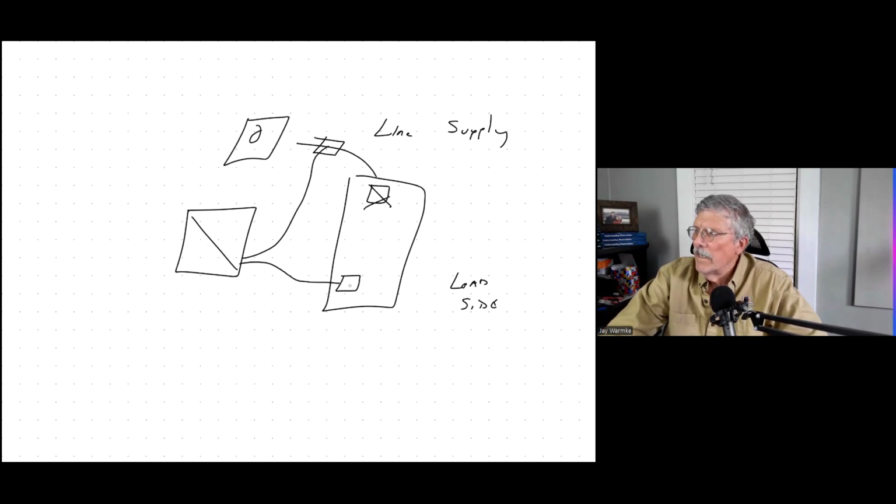It's no big deal. In fact, we'll do that in our labs when you're here in Marietta. It's a piece of cake. Just turn off the main breaker, attach your wires to another circuit breaker, and snap that puppy in there, and you're fine. Easy peasy. But if I have to make a line side connection, I've got to contact the utility. I've got to have my service turned off.